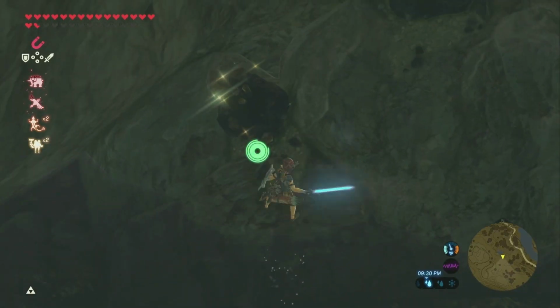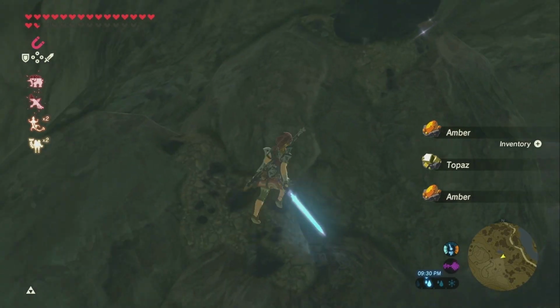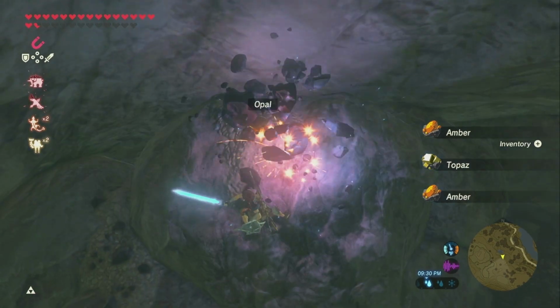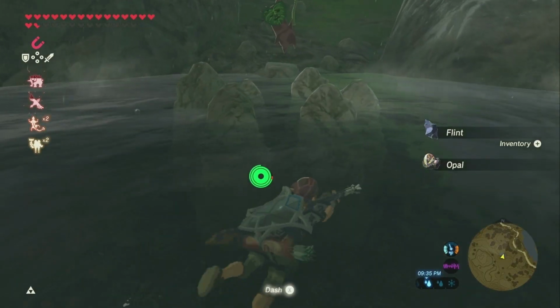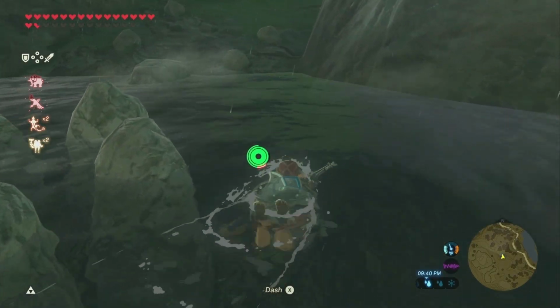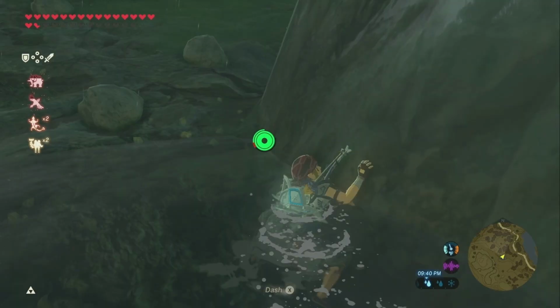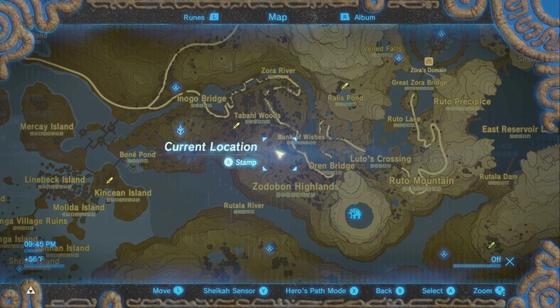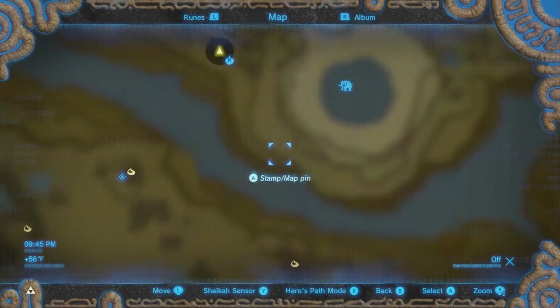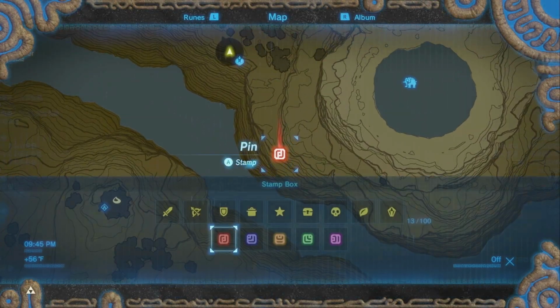Circulating hot water systems. This system provides constant hot water to fixtures to eliminate the need to flush the cold water in the pipes. More common on larger houses. Additional piping is required as the system requires a return pipe from every fixture. Pumps can be continuous or controlled by an aquastat.